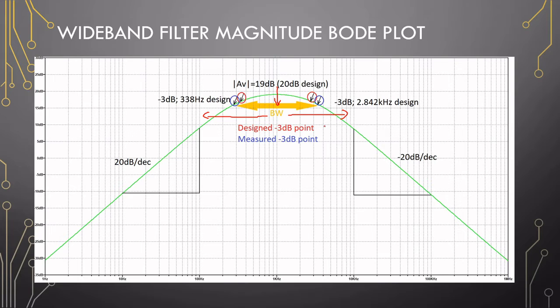If we decrease the Q factor, our bandwidth will be closer to the design parameters and our gain. But if we increase the Q, or basically try to move these sides inwards, our gain will decrease and our bandwidth will not be what we designed for. Okay, so those are things to look out for.